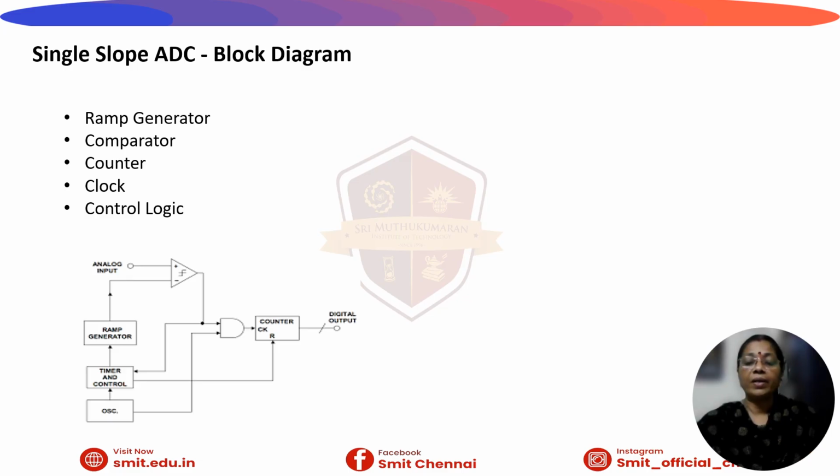Because the ramp increases at a constant speed, the total count is directly proportional to the voltage of the analog signal given. The formula is given as capital T is equal to V in into R into C divided by V reference.